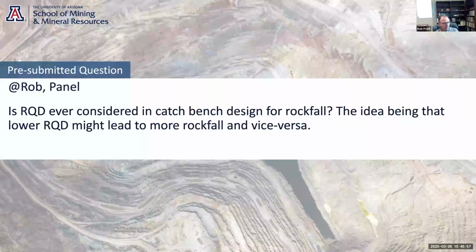When we think of weakened slopes, highly fractured slopes, there of course is the nature of the ground itself, as well as blast damage that contributes to rockfall in a dilated slope. So I think in the sense that the more highly fractured the ground, the more damaged it may be, however it comes about, whether it's the raw nature of the ground or through blasting or mining induced.